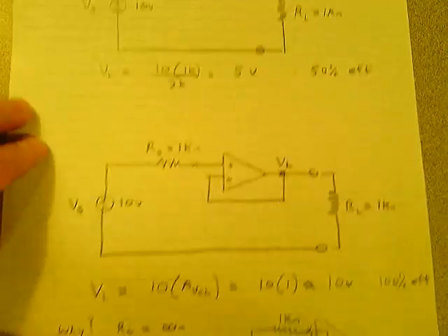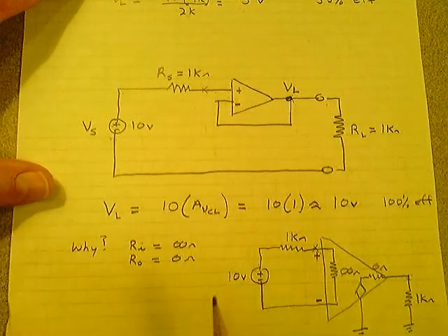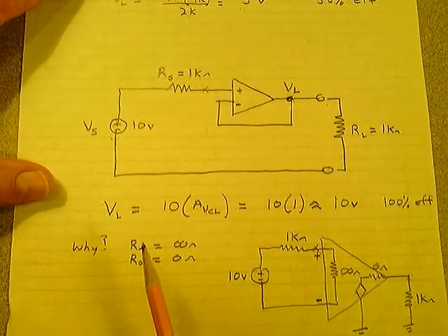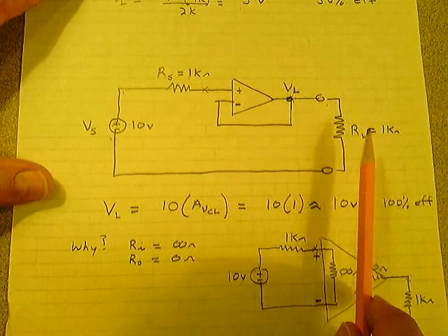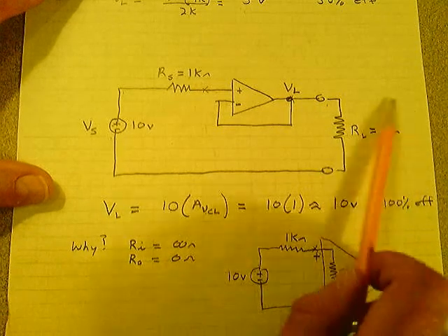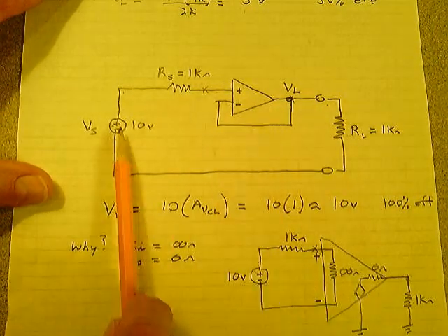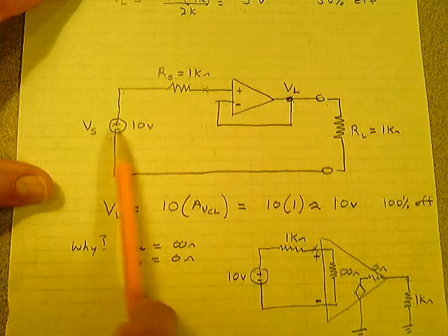Down here, if you put that in the circuit, it does a number of things for you. A lot of engineers will use that. First of all, if something happens out here, or something, this is another circuit that's modeled as a 1K resistor. If this circuit gets damaged for some reason, it might take out this device, but it protects whatever's back here. That's why it's called a buffer.